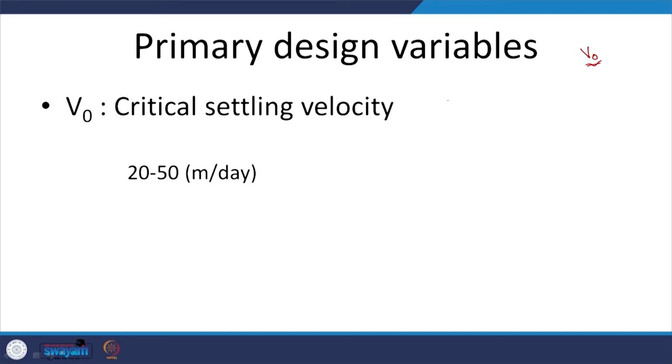So I think we looked at this upflow and so on, right? If my particle is coming in through here along with the water, because of this increasing cross-sectional area as I go up, and Q is equal to area into velocity, Q is the same and area is increasing, then velocity will decrease. Gravity will be pulling the particle down, and as you see, the velocity of flow of the fluid is decreasing as we go up, right?